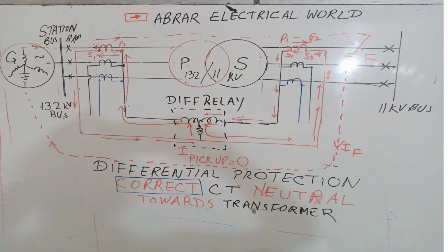Now see, when you have the primary current like this, the secondary current will be in the other direction, and similarly here the direction of the primary current is from left to right, so direction here will be from S2 to S1. Now if you look at this direction of the current, you see this current is flowing like this, returning to the neutral, and the other current is flowing from S2 to S1, then here into the relay, and then it is going back right here.